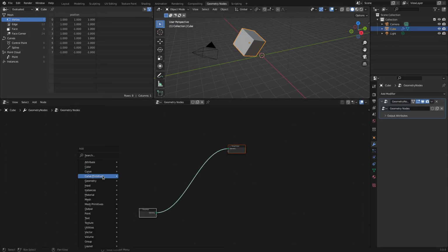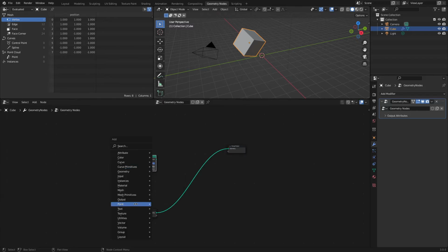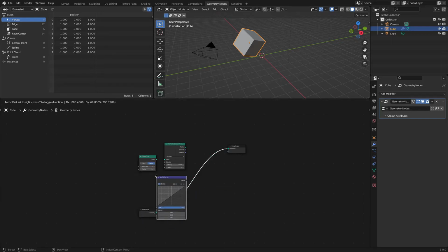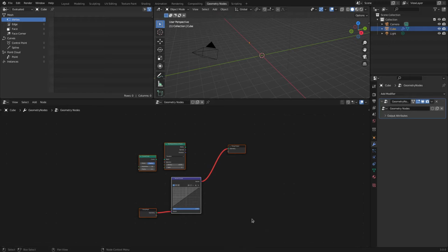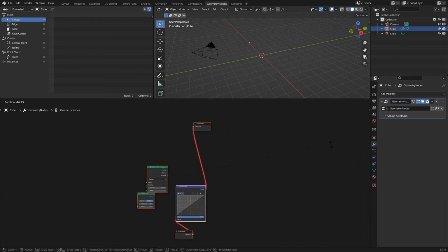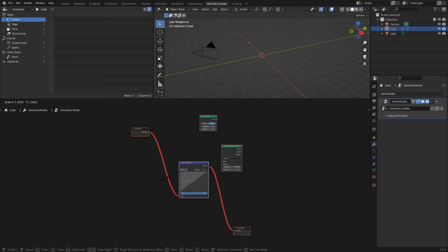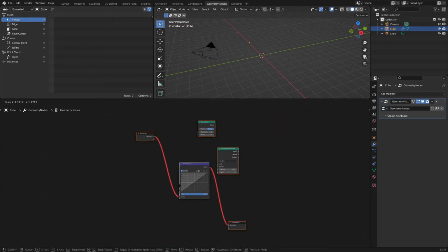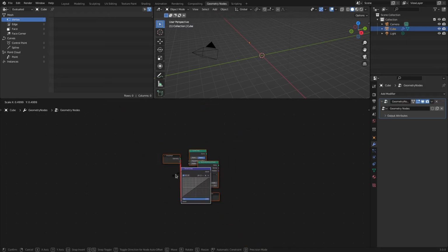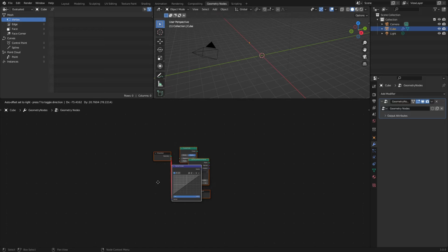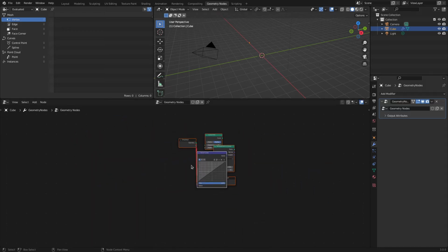And if I add a bunch of nodes, doesn't matter what, just drop nodes all over the place, that works too. Hit R, they're all going to rotate around the calculated center, again calculated from the upper left-hand corner of each node. S is going to spread them out. And G is grab, and I can move them wherever I like. Okay, so that is node transformation. Let's jump over to the next topic.